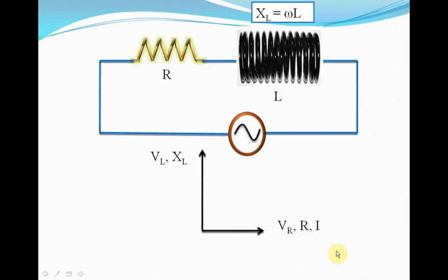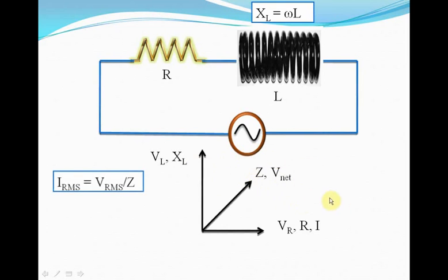So first of all, let's see what's happening by drawing a phasor diagram. As you can see, VR, the potential difference across the resistance itself, and the current are all along the x-axis initially, the phasors I mean. Similarly, the potential difference across the inductor initially leads the potential difference across the resistor by 90 degrees. So does the value of XL, the inductive reactance. And this is the value of Z, isn't it? So as you can see, impedance is somewhere between XL and R here.